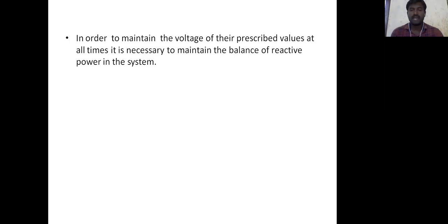If the reactive power generated is greater than the reactive power absorbed, under that condition the voltage goes up. And if VAR generated is less than VAR absorbed, the voltage goes down. VAR means reactive power, reactive volt-amperes, nothing but reactive power.